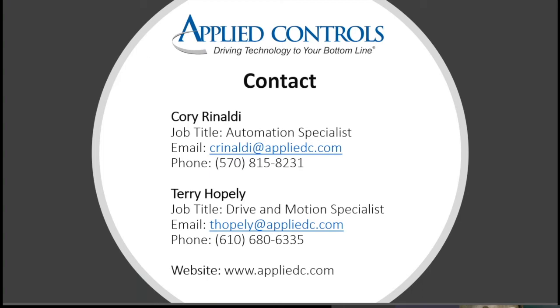So Isaac Hayes asked, does this back up safety functions as well, Corey? Yes, I believe you would need the safety password though as well. So if you had a safety PLC with safety code, there would be a separate password associated with your safety portion of the program, which would prompt you when uploading that. So for backup, there's no safety obviously with the panels, but with the controllers and the drives, then that's a different story.